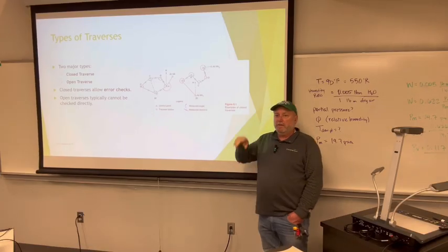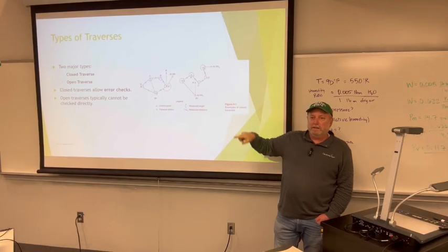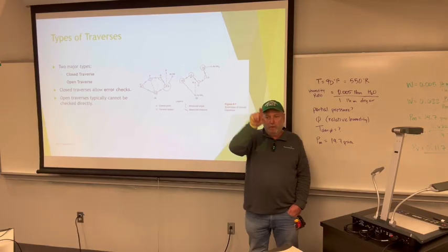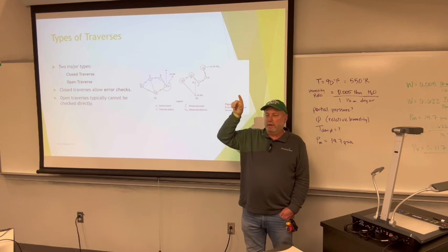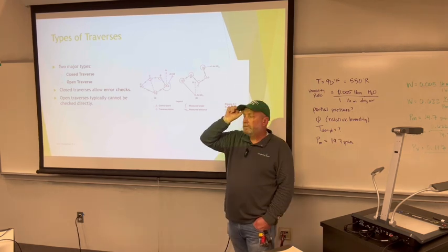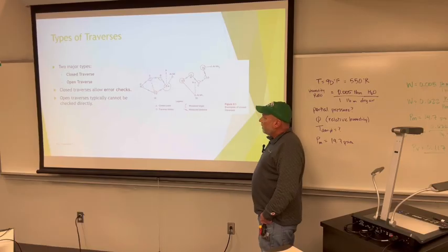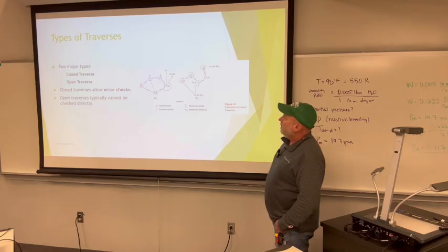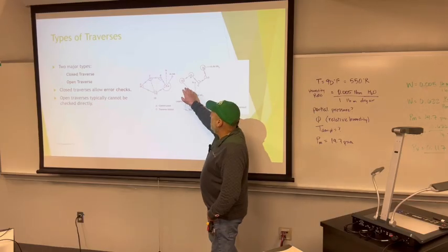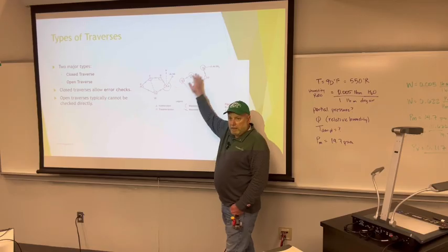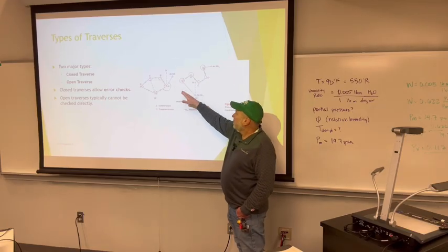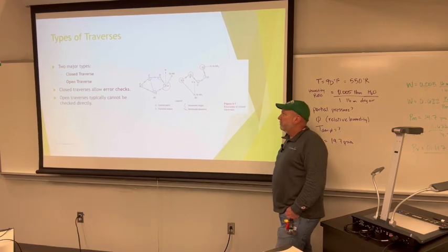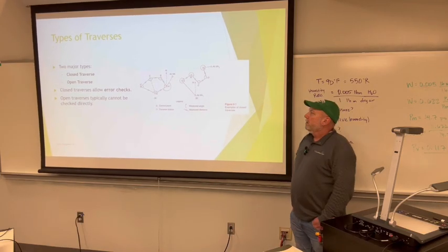Like the survey plat where we start at a point of beginning and we draw all the bearings and distances around the property. With a traverse, same way. You start at a point, you go around, draw your property, and you tie back in. An open traverse is where you maybe have two known published monuments at either side and you traverse, just kind of run angles and distances from one known point to another.